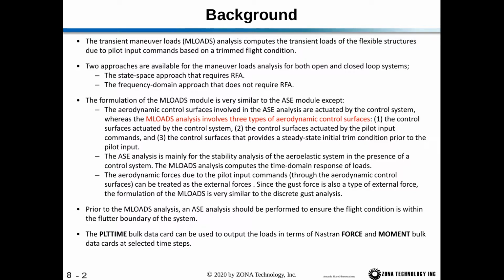Secondly, we have control surfaces actuated by the pilot input command. And lastly, the control surfaces that provide a steady state initial trim condition prior to the pilot input. And ZAERO segments your control surfaces that you define by the AESurfZ card into these three different types. But from the user input, when you set up the analysis, for example, you could just have one control surface, one AESurfZ card, an elevator, for example, and it can be used by all three different types.